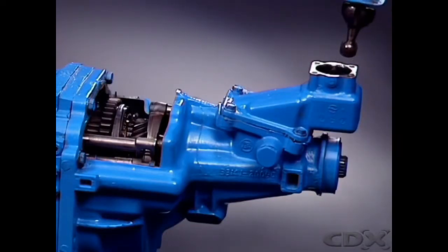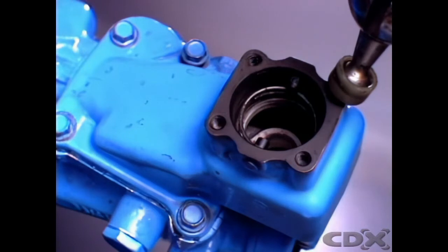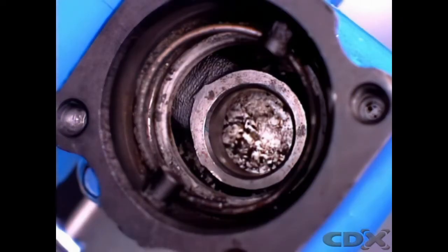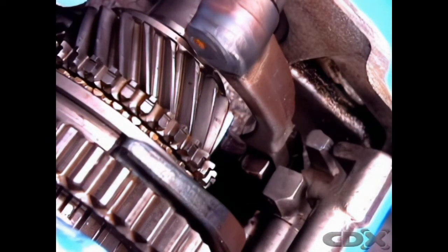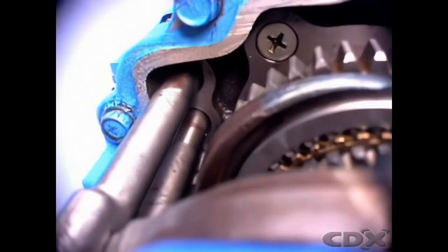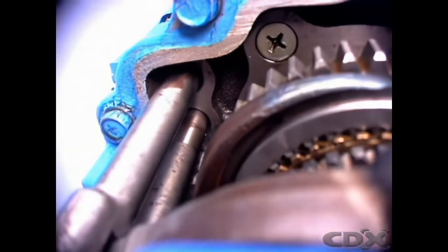It can also be mounted in the top of the gearbox, where it acts through a ball pivot in the top of the extension housing. In this design, the lower end of the gear lever fits into a socket in a control shaft inside the transmission extension housing. A short lever on the other end of the shaft is located in a selector gate formed by slots in the 3 selector shift rails. They are supported in the casing and are moved backwards or forwards by the lever.